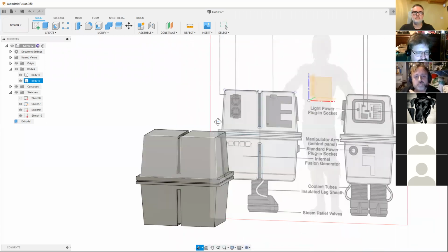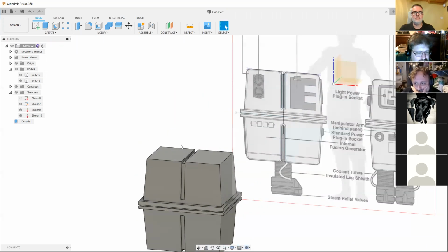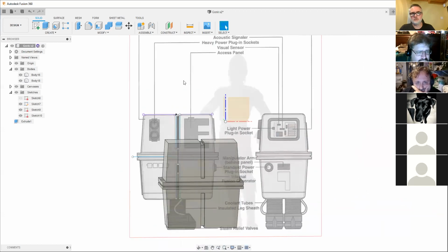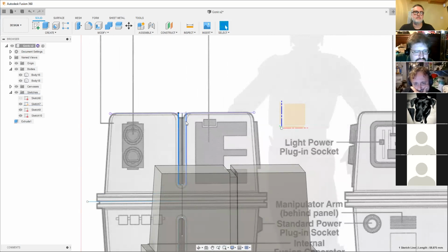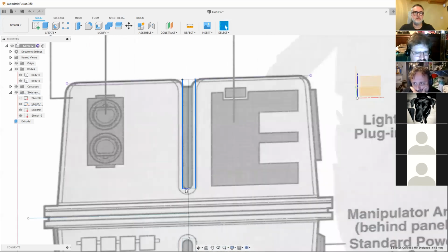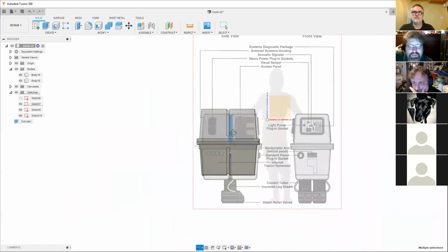And do we close this polygon? We're using it as a cut tool, so all we need is that U shape. Okay, so then just finish sketch and then let it go. Yeah. Okay. And then you can use that as a cut tool. All right, thank you. No problem.